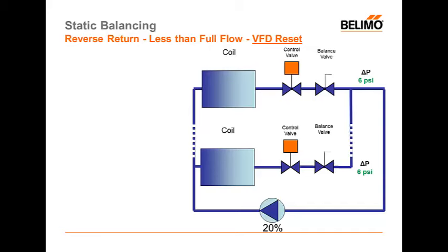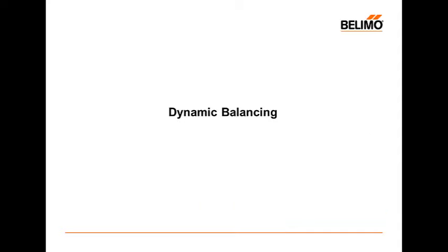Again, if we reset this thing, we'd see pretty much the same thing. We're going to reduce the overall pressure because the flows are lower, and then we have a real nice clean system if we use VFD reset in addition to a reverse return system.